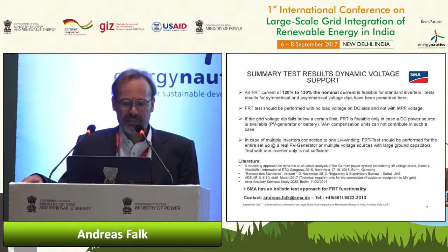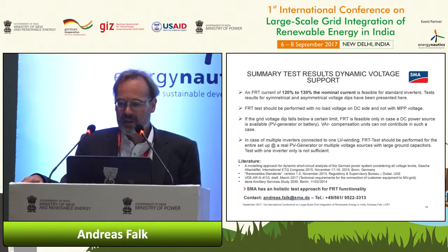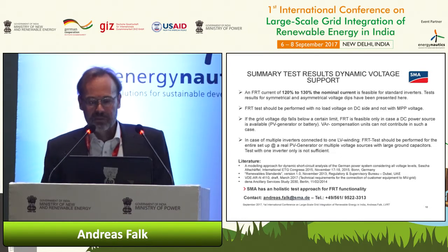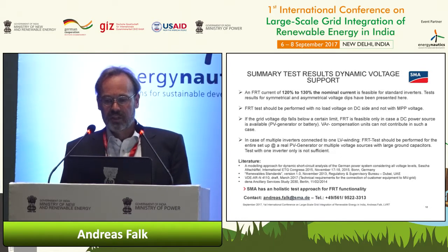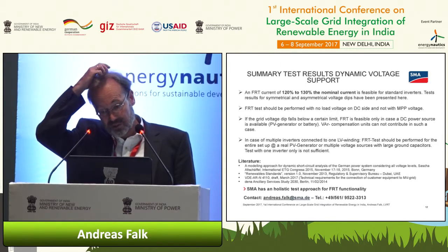In case of multiple inverters connected to one low voltage winding, the fault ride through test should be performed for the entire setup at a real PV generator or multiple voltage sources with large ground capacitors. A test with one inverter is not sufficient.